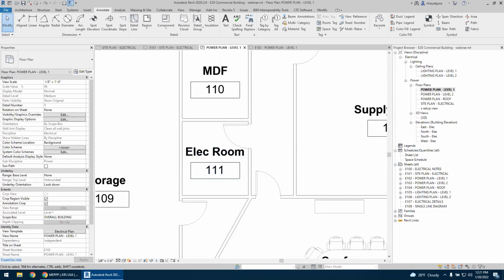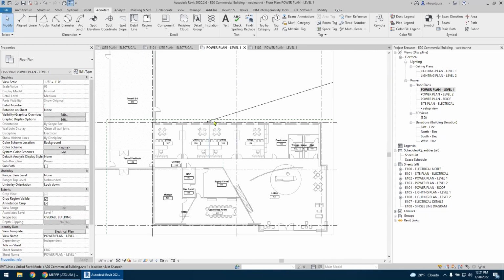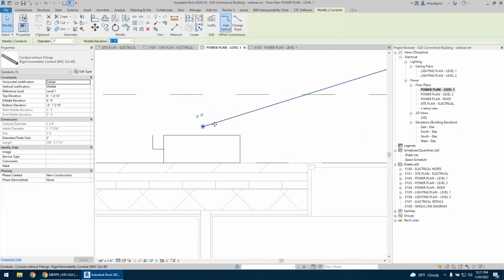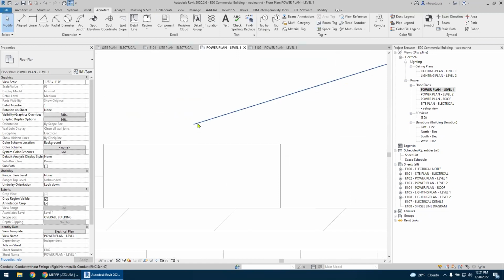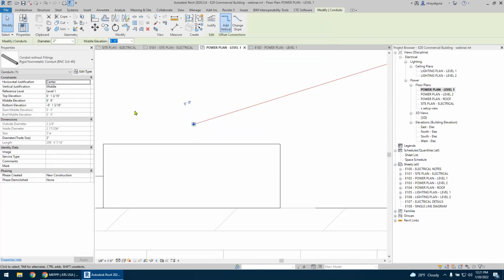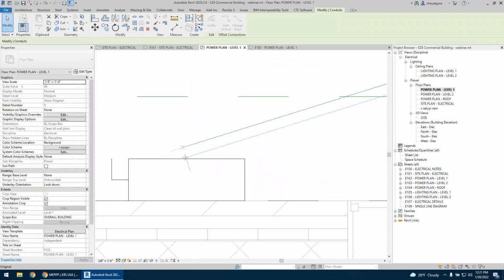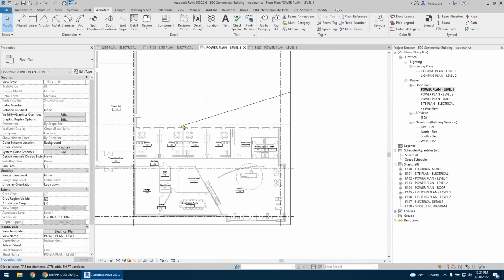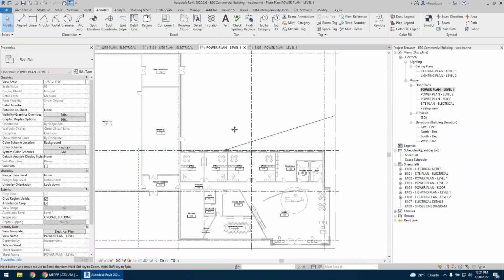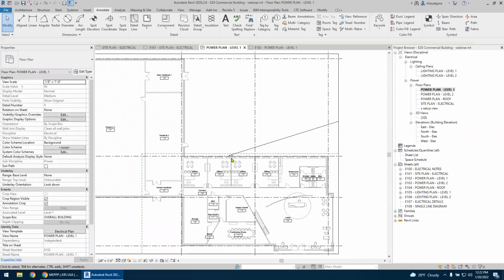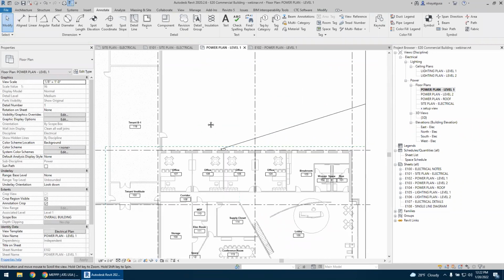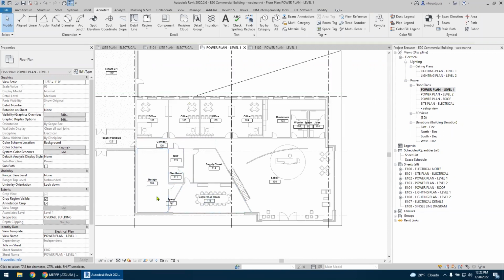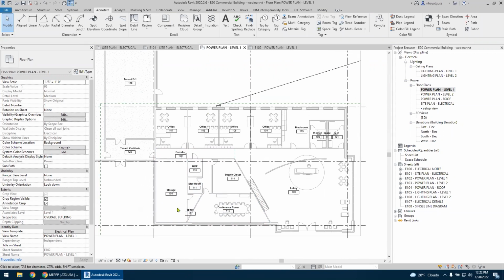Hey, I just noticed, Chris, you asked, do I need a conduit connector in the family? Yes, if we're going to connect conduit. I usually don't draw conduit. Sometimes we do. Usually that's just a single line thing. This, I'm not even connecting it to this equipment. I could figure out where it connects and try to make it. But for the level of design, level of modeling most electrical engineers are being paid to do, that's sufficient. And notes will carry the day. Specs will carry the day. If we're going to get more advanced and do more conduit routing and connecting and having to show big stuff, yeah, absolutely.